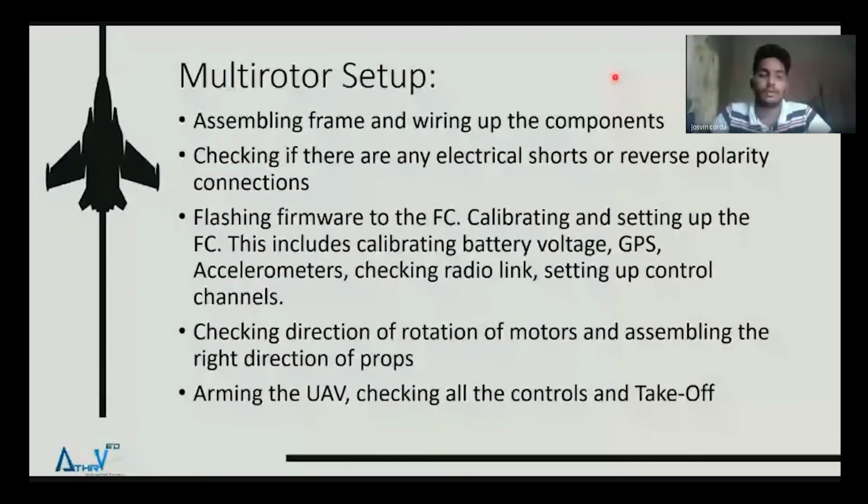And coming to UAVs, there's always a thing called arming. That is, after you connect the battery and the quadcopter initializes, the pilot must manually arm the quad. That is by moving a switch. Arming the quad tells the UAV to be ready for takeoff.